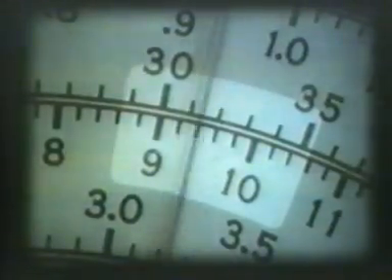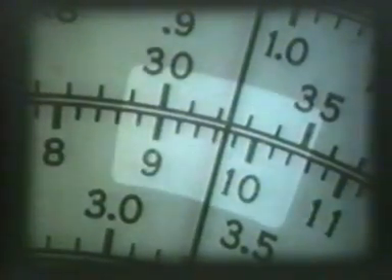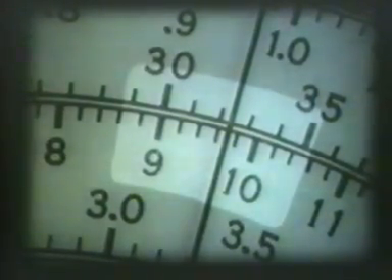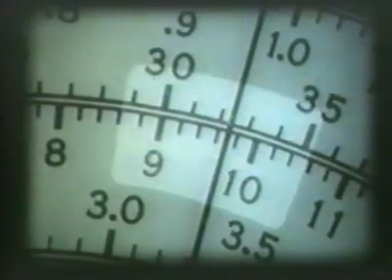Now we are ready to measure the electric field in the bar. I'll connect the voltmeter to the two phosphor bronze points. The voltage between the points is 9.70 volts. The points were set at 1.25 centimeters apart. So the field in the bar is 9.70 divided by 1.25, which is 7.76 volts per centimeter.